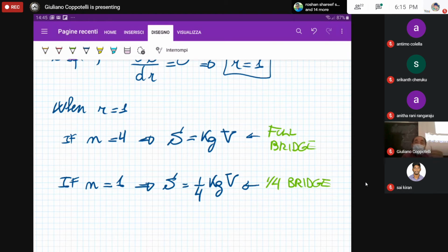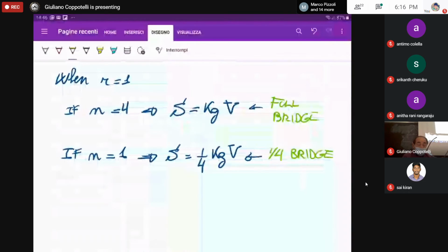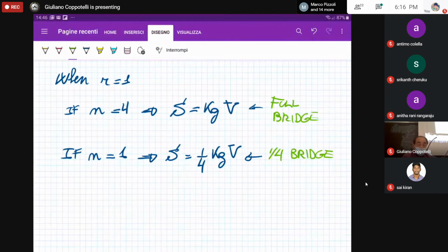However, in order to introduce the maximum power that could be dissipated from your measurement circuit, we have to introduce this maximum power in your equation, okay? In order to do that, we have to distinguish between different operating conditions. That is one leg, two legs, four legs, that is quarter bridge, half bridge, and full bridge configuration. So let's see what happens to the sensitivity when introducing the maximum dissipating power, okay?